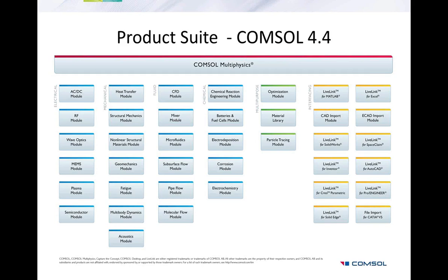Yeah. Okay. That's true. Here's a question, what type of meshes are available? For example, unstructured tetrahedral, hexagonal, structured hexagonal? Yeah, basically all of them. All the meshes that are available in COMSOL are available also in the mixture model. Does that include boundary layers and stuff? Boundary layer meshes, yeah, and structured and unstructured meshes.